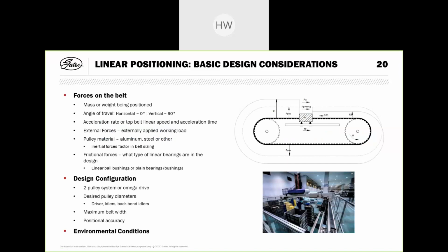Then we also have, in some applications, to consider the pulley material, because when it comes to big pulleys or extremely high acceleration rates, the inertia of the pulley is a factor.